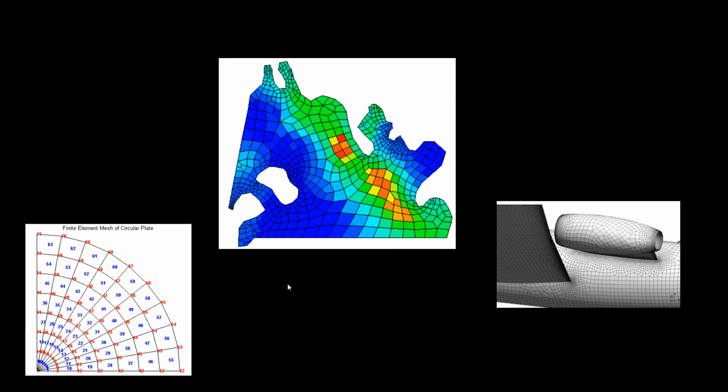Alright, then we have the alternative. These guys are very good at approximating whatever they want to approximate, but the problem is geometry. It gets very cumbersome to create, in a meaningful way, an algorithm that automatically generates a mesh. In the earliest days of the finite element method, this was done by hand. Engineers would be doing the meshing. Nowadays, computers do that, but it's still hard, even for a modern software to do this.